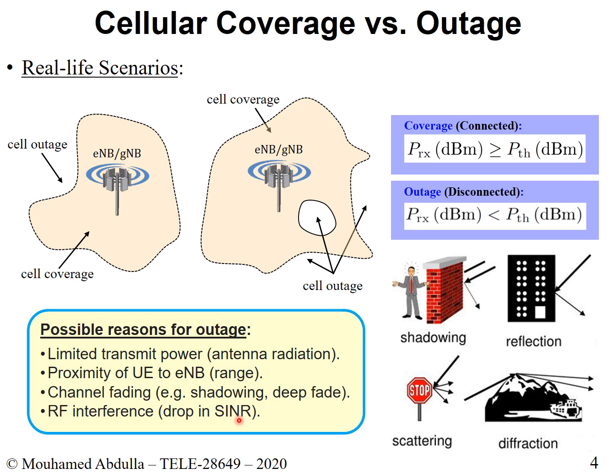If you want to eliminate noise so that we focus only on interference, then you might only look at SIR, and you have your signal on top and you have interference in the bottom. If you have a lot of interference, it will be big, and if the denominator is big, then the SINR will be small. And if SINR is small, that's another reason for getting an outage. Right? So that's also important to know.